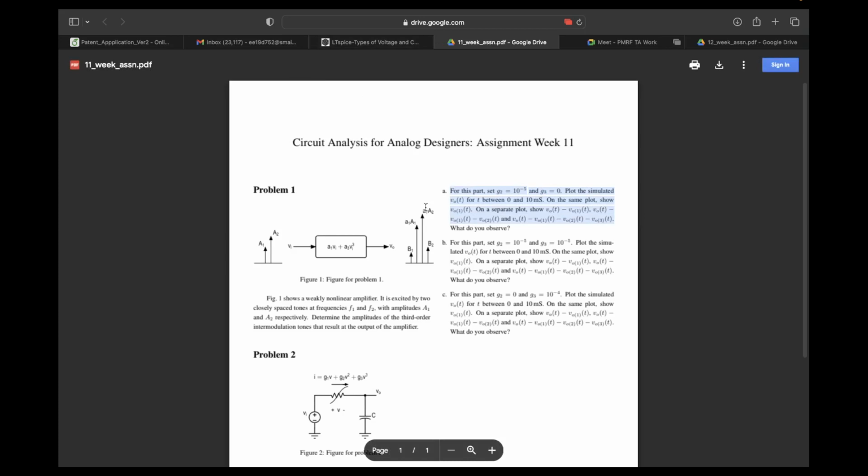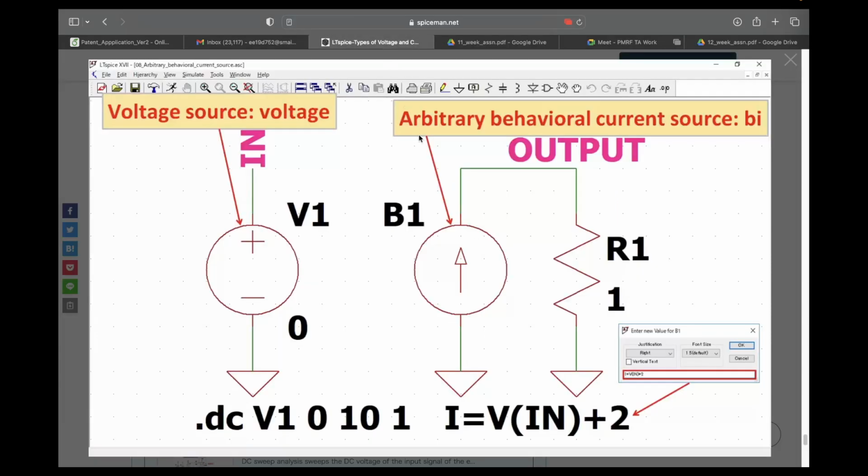Yes, sir. Instead of that resistor, we have to put that current source, sir. Yeah, correct. The resistor you can put. Resistor's value will be 1 by G1, and in parallel to those, you can put these current source. Or the other option is that put the resistor only. So basically, instead of connecting it to ground, you won't connect it to ground. What you will do is you will connect it between input and output.